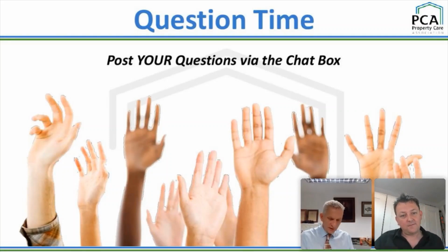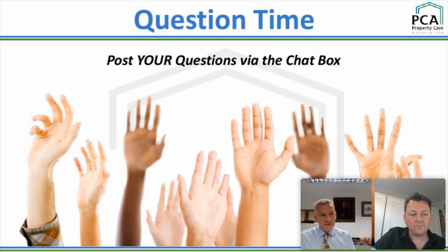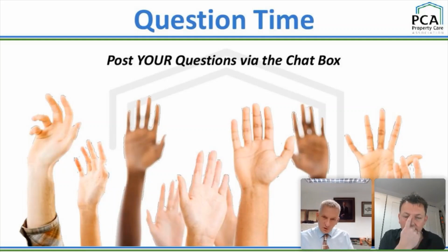Yeah, probably the biggest issue now, which wasn't such a problem probably 20 years ago, is surveyors still have a habit of looking at a cavity wall, and if there's no horizontal cracking, they think there's no wall tie problem. Right. And that was true probably 30 years ago. Because the post-war poorly galvanized wall ties, wire ties often, small section, had not yet begun to rust severely. They are now rusting severely, but they don't cause horizontal cracking, right?